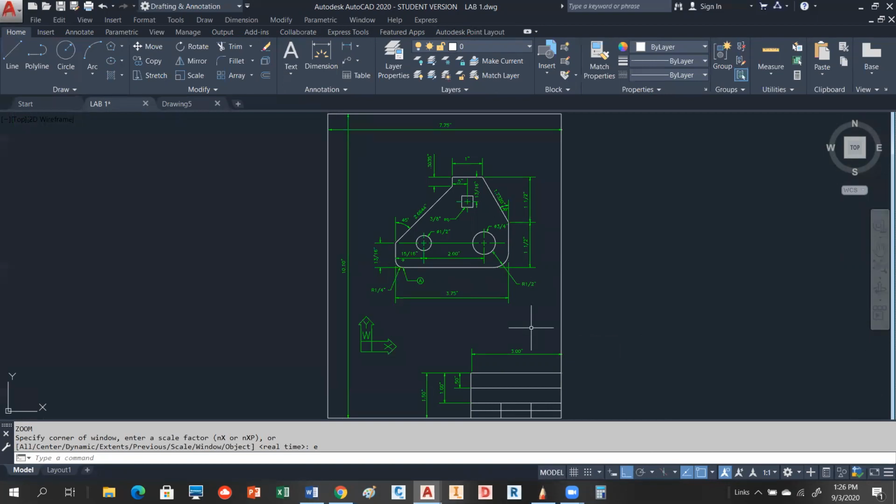So we have other types of zooms here. The other type is called the zoom window. With a zoom window, you can always zoom in, but you can't zoom out. What you're going to do is pick 2 points, much like that. The size of that window will determine the amount of magnification. So that would be less magnified than, say, that.